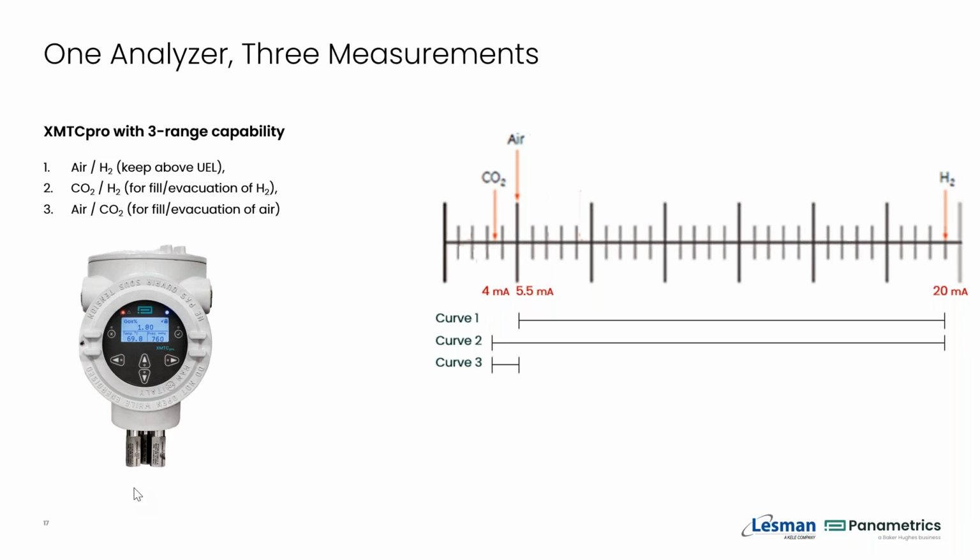In fact, remember in the second slide that we had one of those thermistors sitting in a sealed reference, and that sealed reference is dry air. That gives you your reference point, so there's no need for a flowing reference. But you do require a constant flow of your sample gas. It will not work in a stagnant situation. So you can't use this, let's say, as an area monitor, because you won't get diffusion up into the measurement cell. You do need to pull a sample through the transmitter. So I'm hoping that I've answered the question 2 different ways.